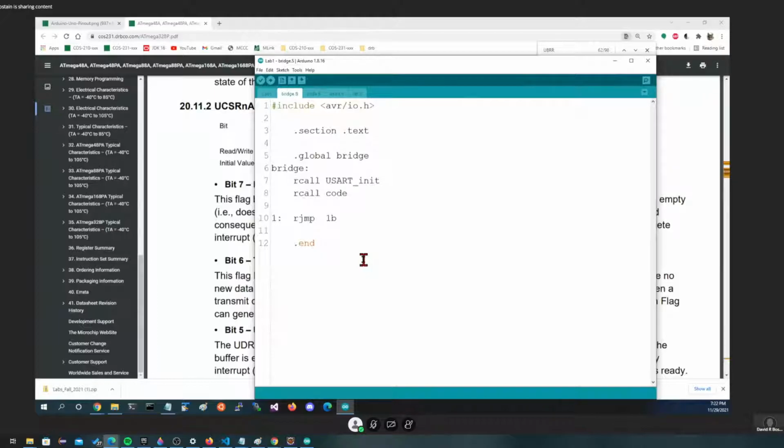Why is it important that it do those two things? You can answer, or anybody else. Because our code is using calls from the USART file, so we need to initialize those first. Yeah, that's good. Really the real hidden reason underneath all of it is a reset could happen at any time.